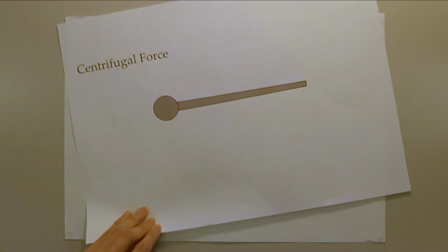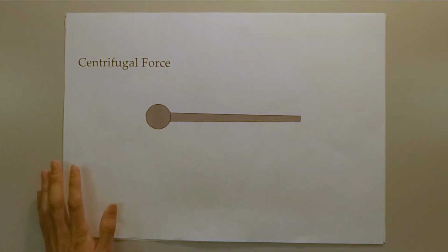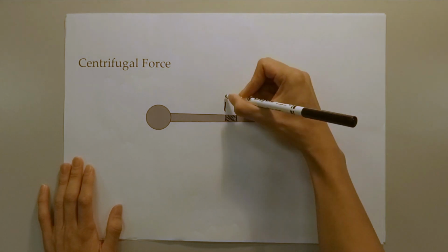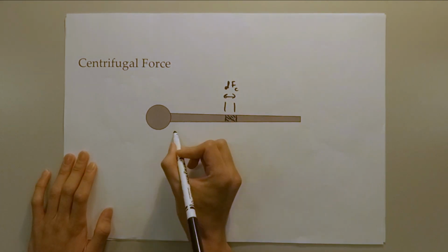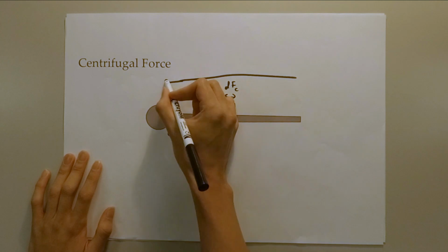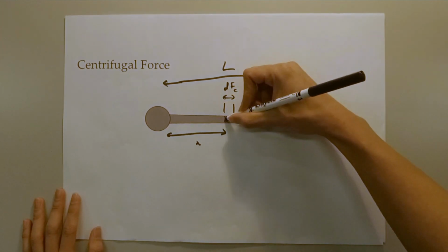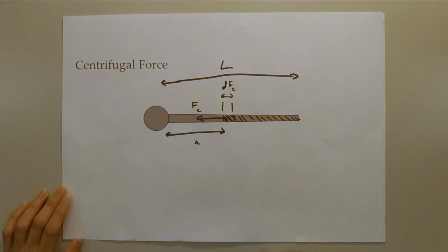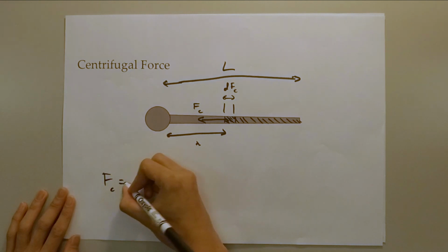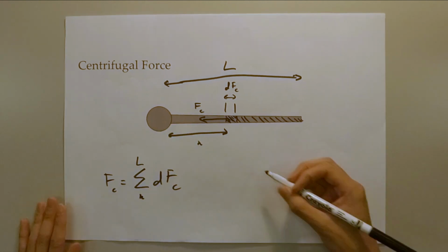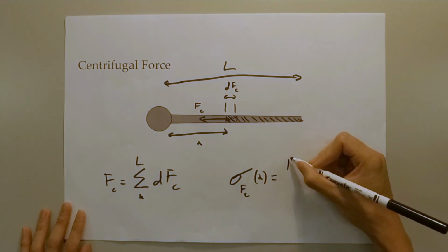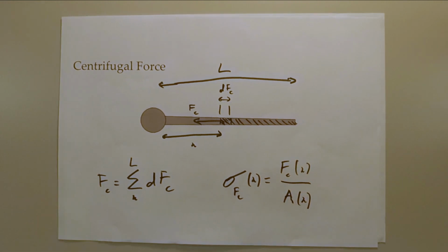To ensure that our turbine blade will not fail during testing and operation, a detailed structural analysis was required. Using the blade sections that were split earlier, we first calculated the stress due to centrifugal force along the blade section. We first calculated the force at a certain section of the blade, and then, to get the centrifugal force at a specific radius of the blade, the force is summed towards the root of the blade.